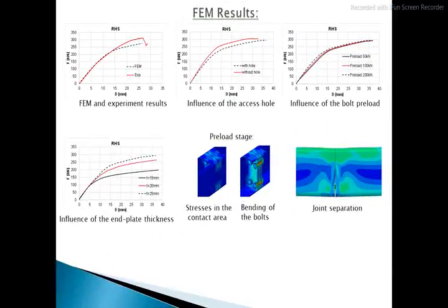By performing the finite element analysis, the force displacement curve is compared to the one obtained from the experiment, as we can see on the first picture on the left top. The influence of the access hole was also studied, with hole and without hole, and the influence of the preload of the bolts.